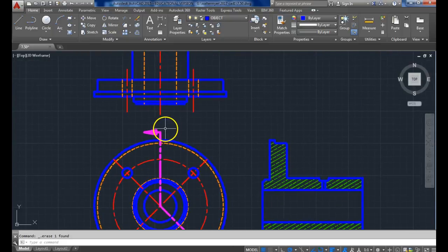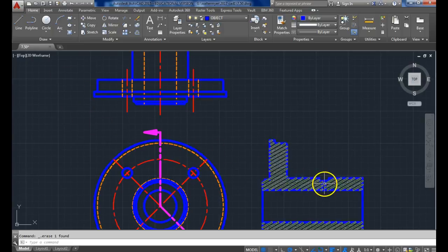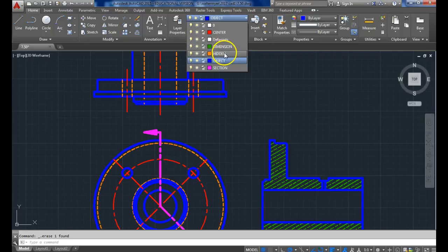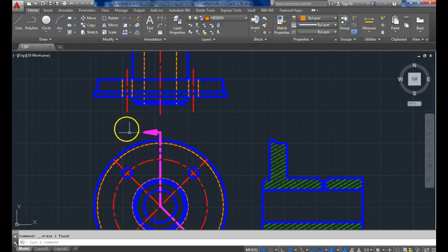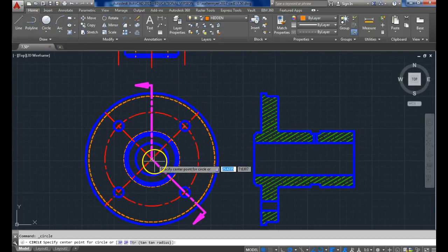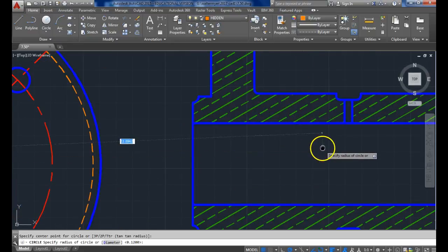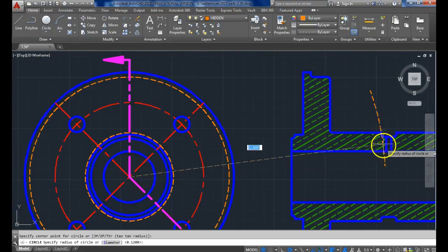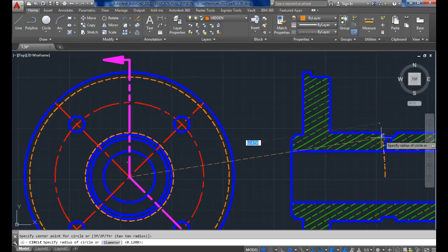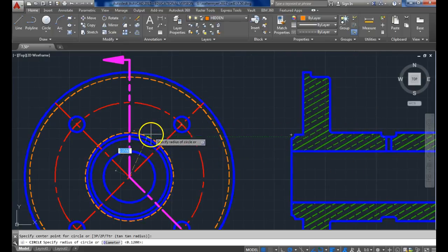That is one of the things that I need to bring down through here. Alright, same thing with the groove. Now the groove, if I remember correctly, lines up with the line that's already there, but I'll double check. So if I do a center radius, click my center point, and touch the bottom edge of the groove, bring it flat over, keep it lined up.